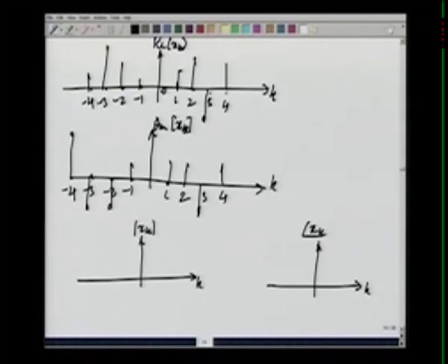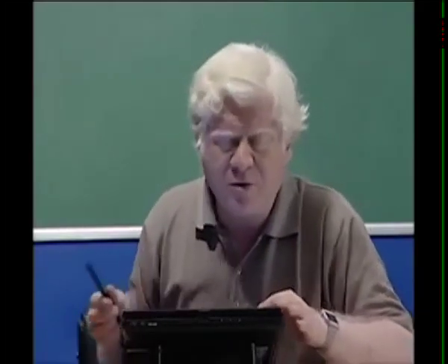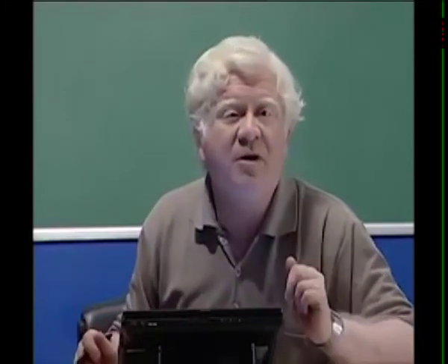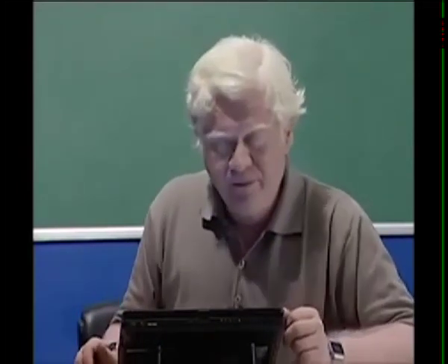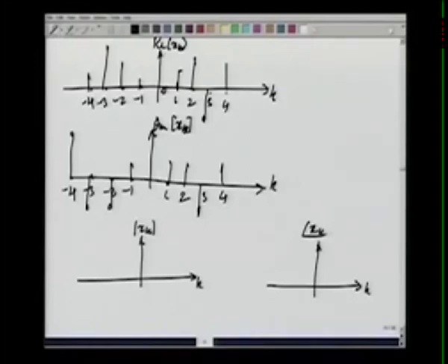Fine, this is what you would have. Now, you see an essential feature here is this. This also is discrete. The magnitude plot is also discrete, the phase plot is also discrete, because it is available for only discrete values of k. So, you will get some plots which look like the real and imaginary plots we have made, but then certain patterns can be discovered. When x t is real, conjugate symmetry holds, and in such a situation you will find that mod x k is even. Let us list all these properties over here.